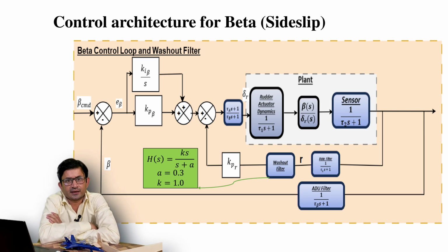I already explained that you can have an unstable pole in the open loop case but cannot in the closed loop case. So in the closed loop case, all the poles should lie on the left half of the plane. Let's say you have done it beautifully, but it may be far from the origin. That means you have stabilized it more.